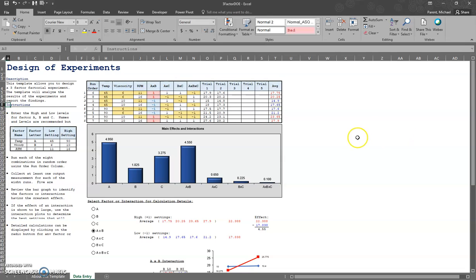So design of experiments is kind of a 6 Sigma black belt, sometimes master black belt level. And I'm not going to get into the details of how it all works because it is a little proprietary. But here what we have is we've named different factors that we're looking to test and see the sensitivities, the main effects, and the interactions between. This informs a design of experiment plan on what settings we're going to put at them, high settings, low settings. And here we've annotated what those settings might be. For temperature, it might be 45 degrees to 90 degrees. Viscosity, if we're changing some viscosity setting in a fluid, and then rotations per minute, we can also change that.